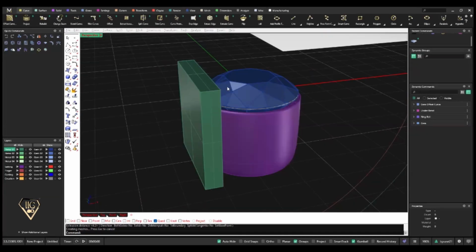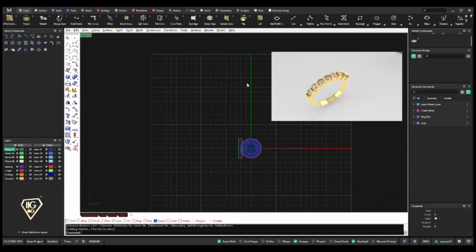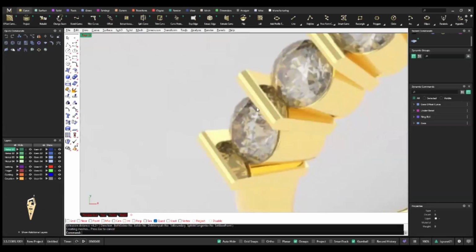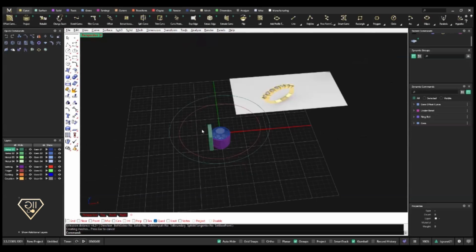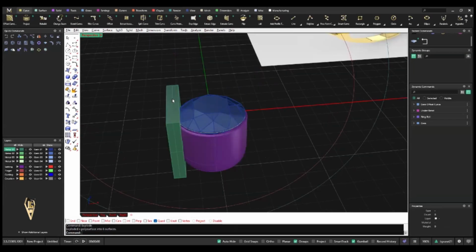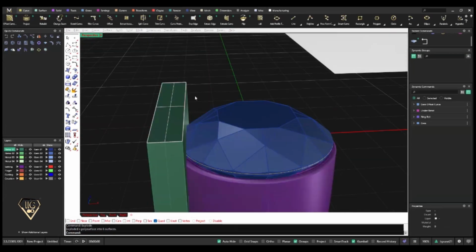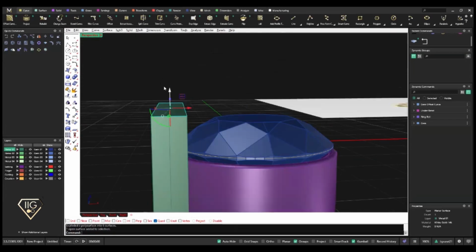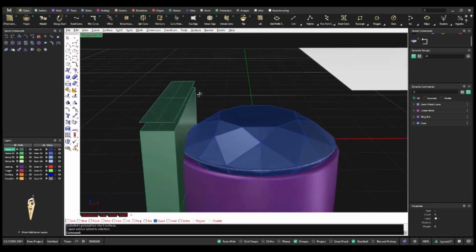Okay, now अभी इतना हो गया इसमें. Now if you can see in an image, यहाँ पे ना शार्प एंड नहीं है, यहाँ पे एक लाइक स्ट्रक्चर है, डोम स्ट्रक्चर जैसा है. Okay, तो इसके लिए we'll go in perspective, we'll select this thing and we'll just do explode. Okay, तो explode and ये टॉप सर्फेस, सो इससे क्लिक करेंगे सर्फेस को एंड इसे हम लोग अप करेंगे, move up करेंगे 0.2 एंटर लाइक दिस.